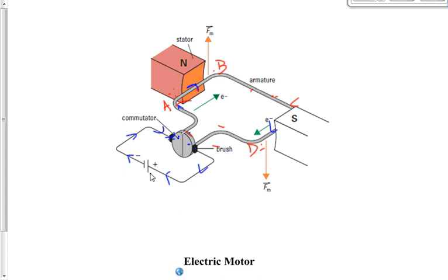Agree? Let's look at CD. Wire CD here. There's a current out of the page for this one, right? It goes around into the page, comes around out of the page. Thumb in the direction of the current from C to D. Fingers, field. Palm points downward. So AB is pushed up, CD is pushed down.